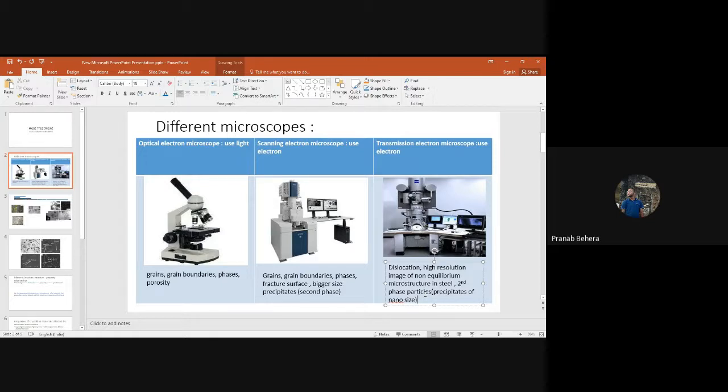See, dislocations are pinned by. Can you people tell me how dislocations are pinned? By the small precipitates. The small precipitates have pinned the dislocations. And just look at the upper images. This is a very beautiful image of a precipitate sitting along the grain boundary, or sorry, lath boundary, martensitic lath boundaries, right? Okay, anyways.